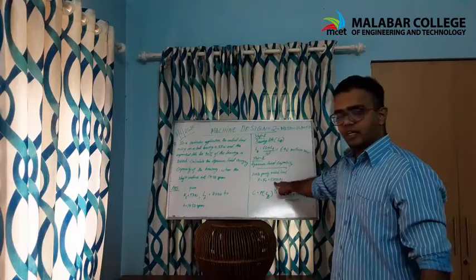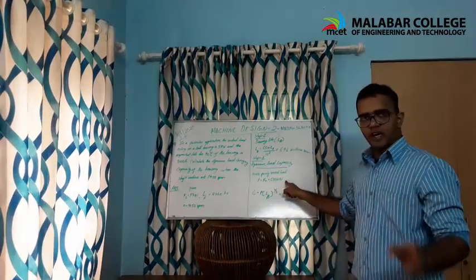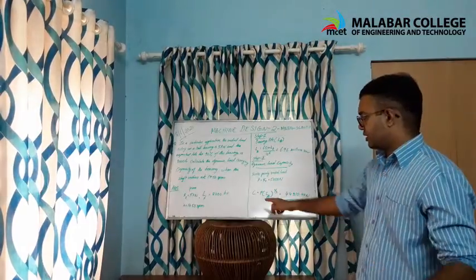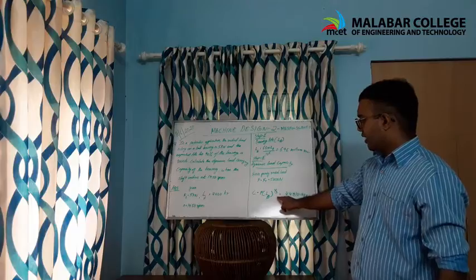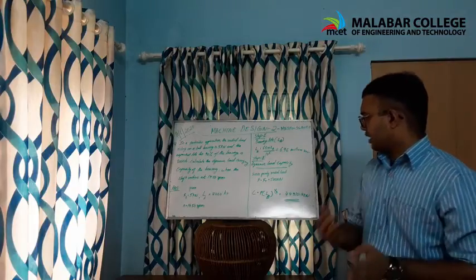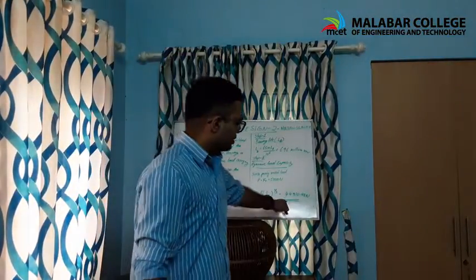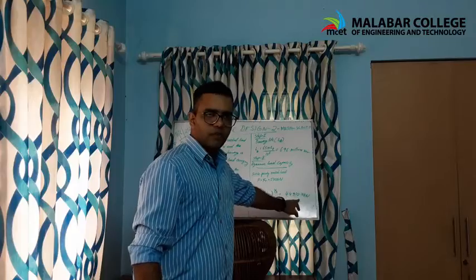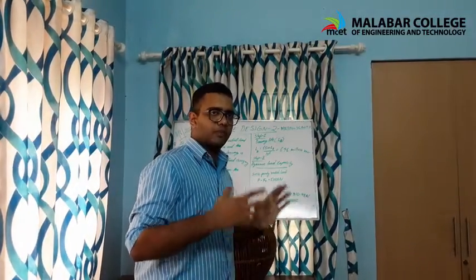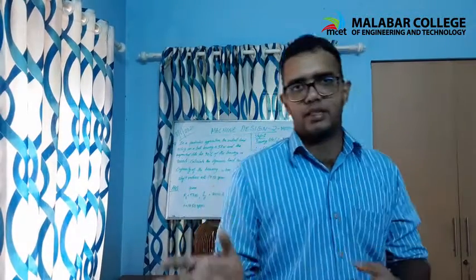So P is equal to Ft, which is given as 5000 Newton, and we know the data book equation: C is equal to P into LB raised to 1 by 3. On substituting it, the load capacity of the bearing is 44,310.48 Newton. After that load limit, the bearing will be destroyed. That's the meaning of the load capacity.